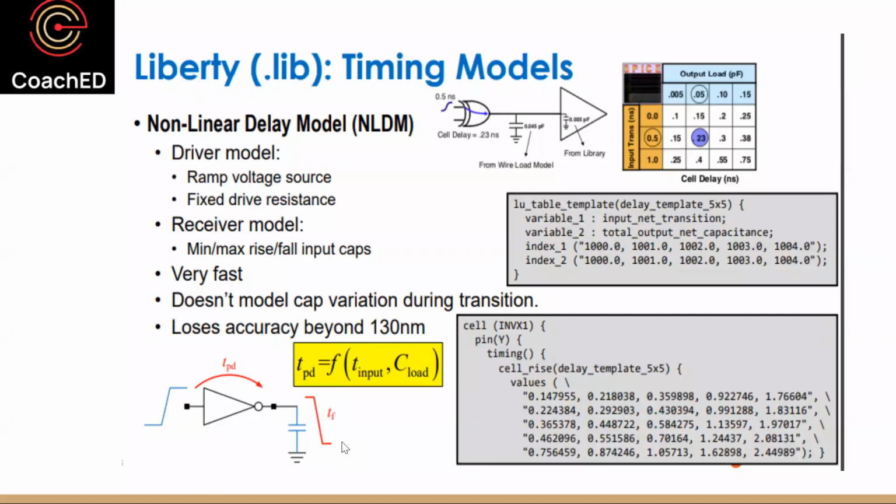So as I was describing earlier, the only thing done for the output is we change the load, just the capacitance. So I don't care whether it's a wire or a gate, because I only care that it's a capacitance. For me, the delay matters only as a capacitance. Additionally, I vary the transition of the input. Now, if I have 4 possible values on the input transition, and let's say 5 possible values of the output load capacitance. When I say output load, I mean specifically capacitance values.